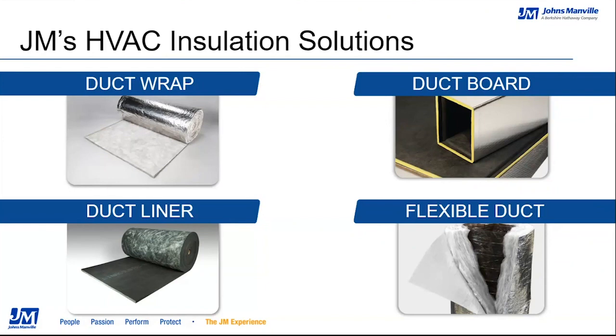No sheet metal needed there. On the bottom left-hand corner is our duct liner product. We have a lot of different iterations of duct liner. Here at Johns Manville, duct liner is a material that goes on the inside airstream surface of a sheet metal duct, and it is mechanically fastened and glued down to the metal. That's the number 1 reason for duct liner usage: acoustical control.